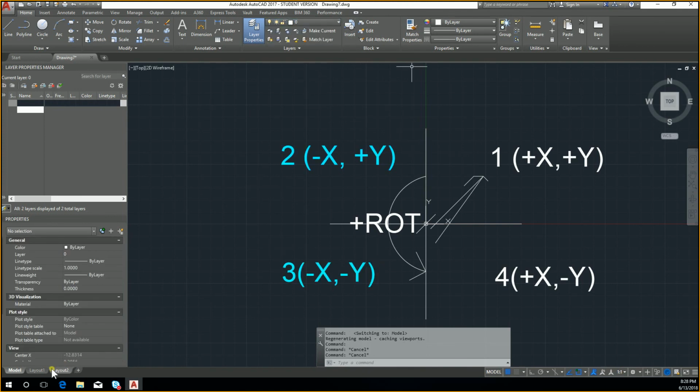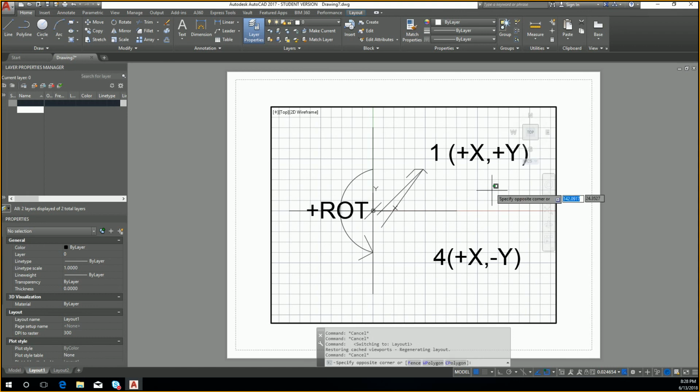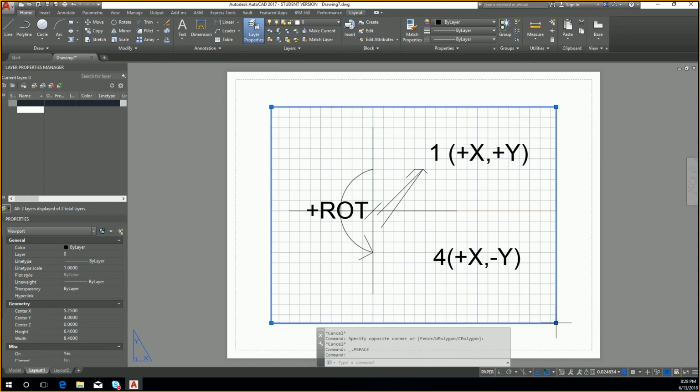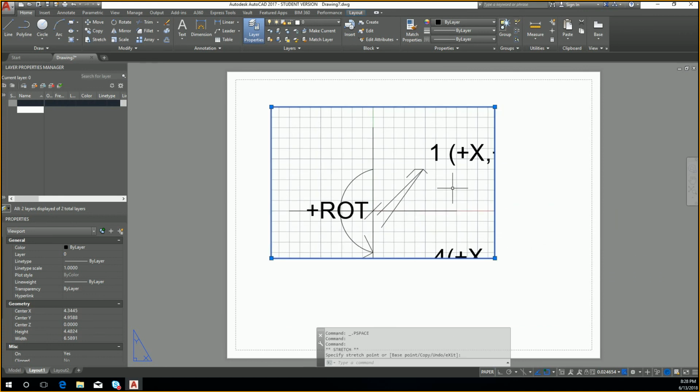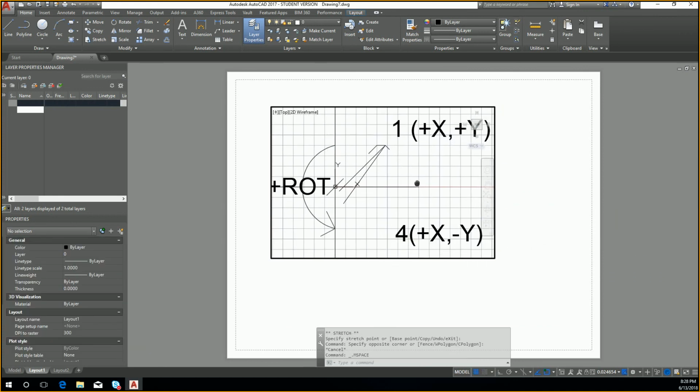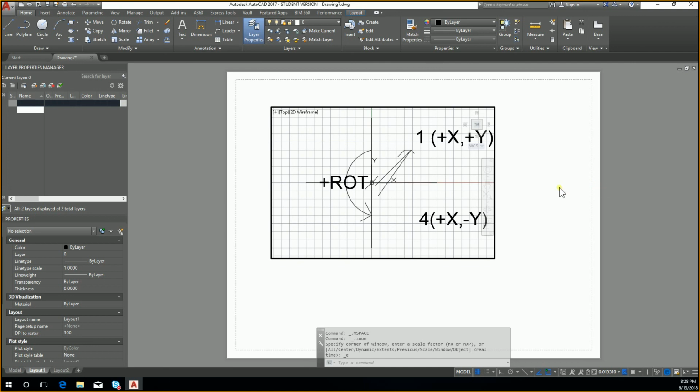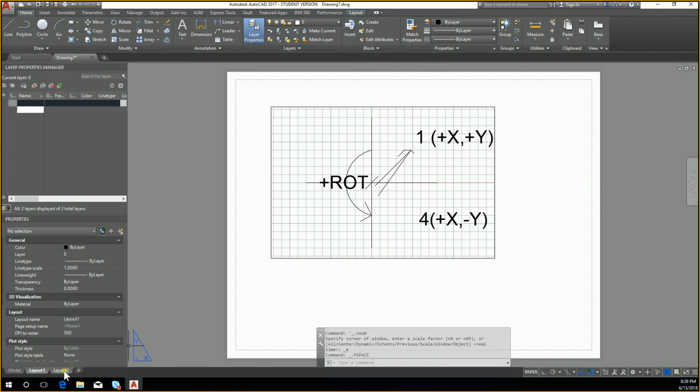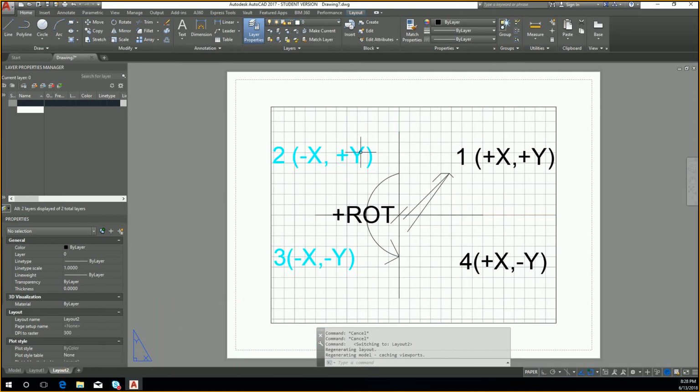So that was the intention of, let's say I want to do a detailed drawing of just this. So I've got my viewport and I just wanted a detail of this only. Then instead of trying to delete or hide the layers, you just freeze that layer within this one viewport. Because then you can still create another viewport. See, that's a brand new viewport. It's all in here still.